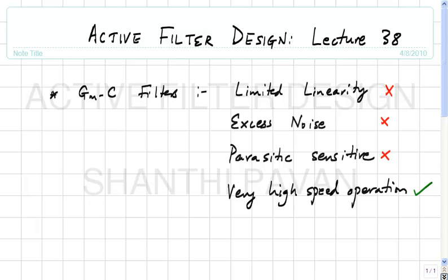You can see that the high speed is coming because of only local feedback, or virtually no feedback, within the transconductors. For example, if you use a differential pair, it's basically an open loop system as far as the integration is concerned. So that high speed is coming with open loop operation, which will naturally mean that linearity of these systems is not great. The moment you attempt to linearize, you get more noise, so you get stuck with what you have. Okay. So a very successful application of GMC filters is in hard disk drives, right,